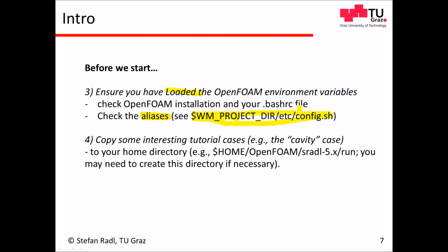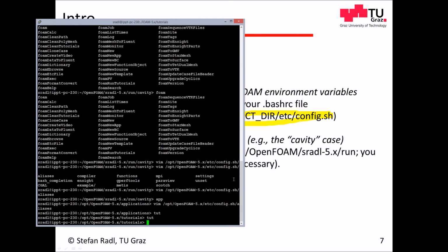Before we start, it's also good to copy some tutorial cases, for example the cavity case, and we will talk about this in great detail. At this point, you can simply type tut and you will end up in a directory with all the OpenFOAM tutorials. We will look at this in closer detail in just a minute.